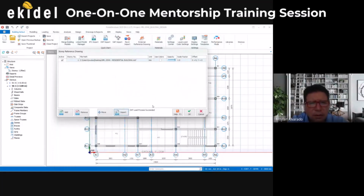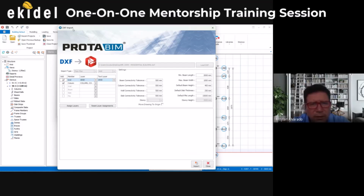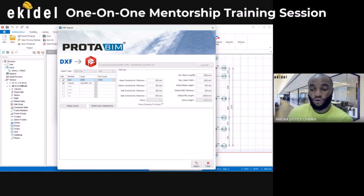Once we click here on import, you see tolerance and the DSF import box. The settings here are just the beam length and all that. You can leave these ones; you can set them later. Just leave these as they are by default. You can change them later.